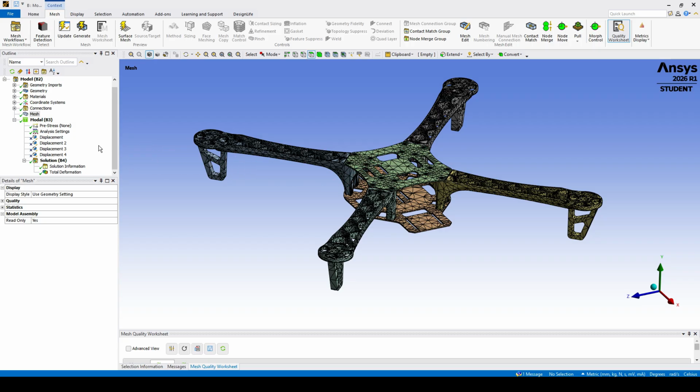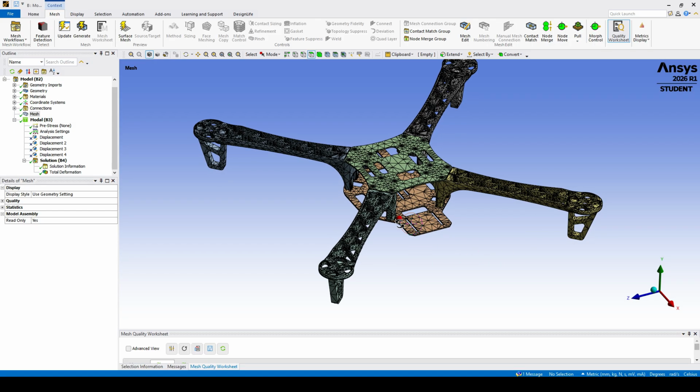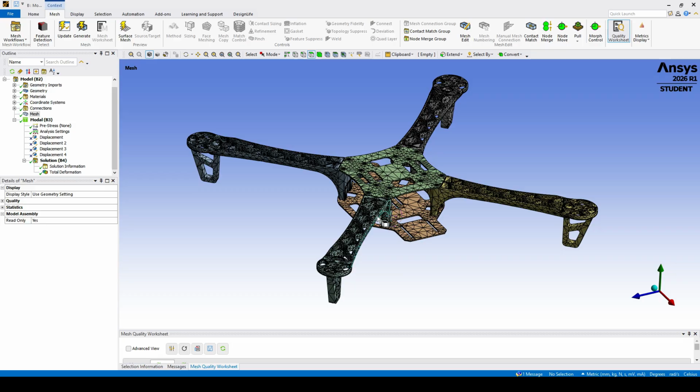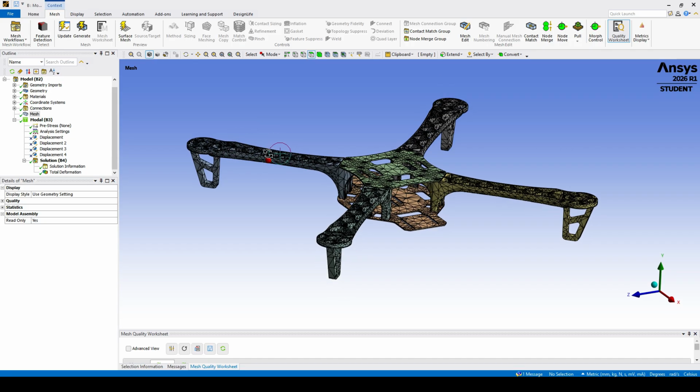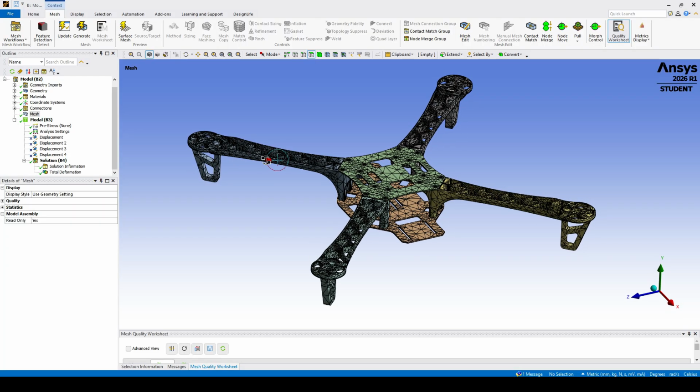After that, you go to the setup, and this is where most engineers and YouTubers make mistakes when doing such studies. In ANSYS, you normally always define a support to prevent your structure from falling out. But while doing a modal analysis, specifically for quadcopters and drones, defining supports or displacement or remote displacement could in most cases make the results wrong.